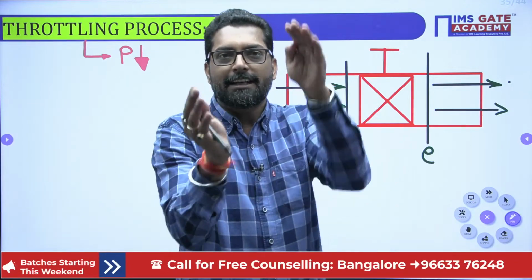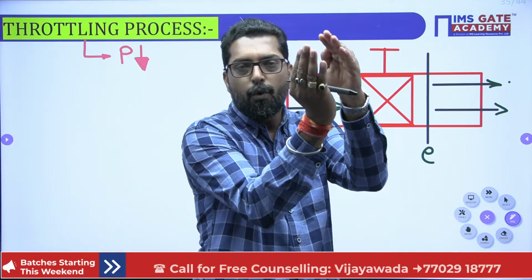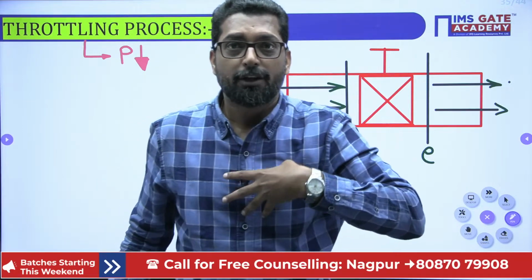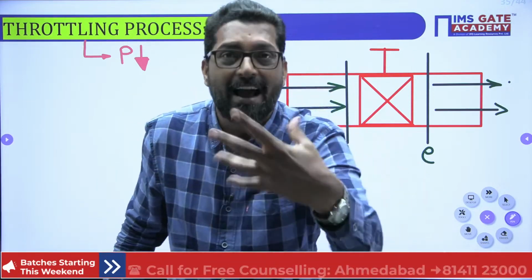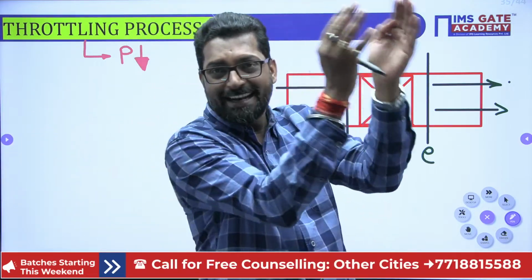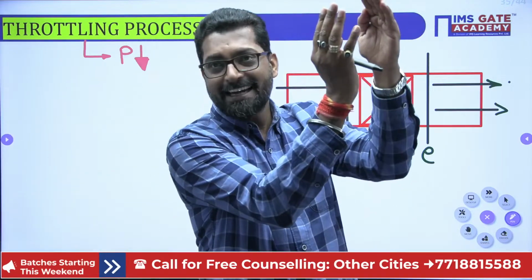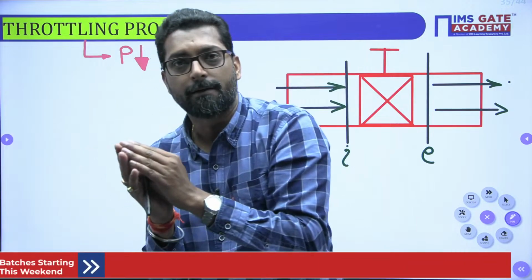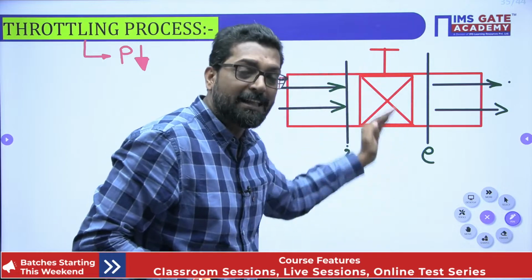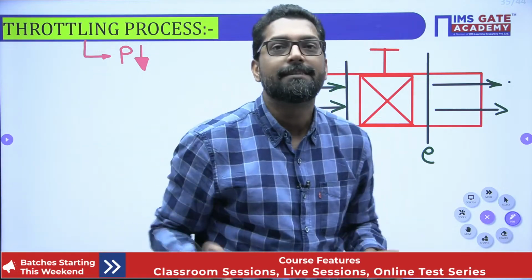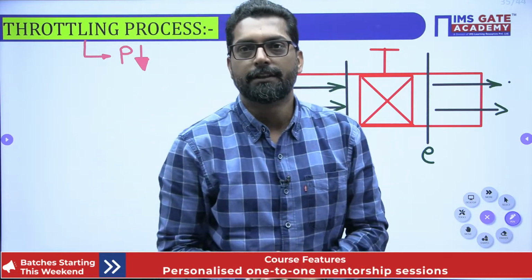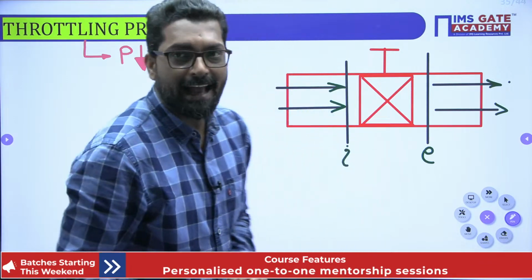Why? Because you know that if the fluid is at high pressure and you want to reduce it to low pressure, there must be a drop in energy. But you don't want to sacrifice energy. The energy will remain the same. That means the energy at inlet, at high pressure, is the same energy we want at low pressure. So during that we have to throttle it. We have to successfully achieve the reduced pressure with the same energy. What is the same energy? Internal energy plus flow energy.